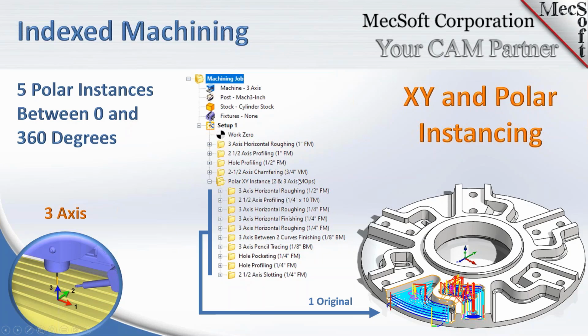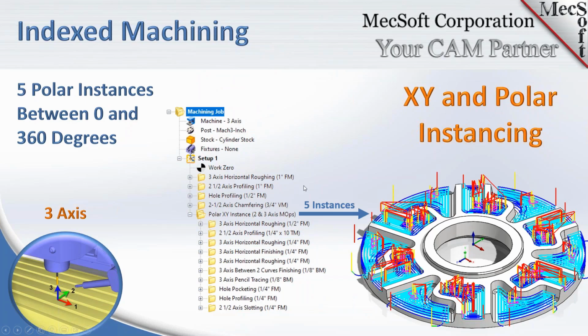This is this folder right here. We just drag and drop the operations in there, and it becomes a polar instancing setup. So let's go ahead, and this is a second view of all of the instances being displayed. If you select, after you move all the operations in the Polar XY instance folder, just select the folder and all of the instance toolpaths will be displayed. And when you post, those will all be posted out as instance 1, instance 2, etc.